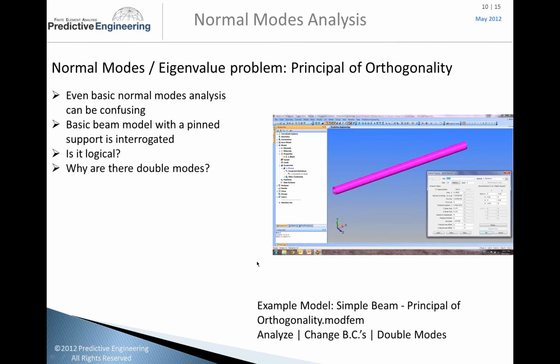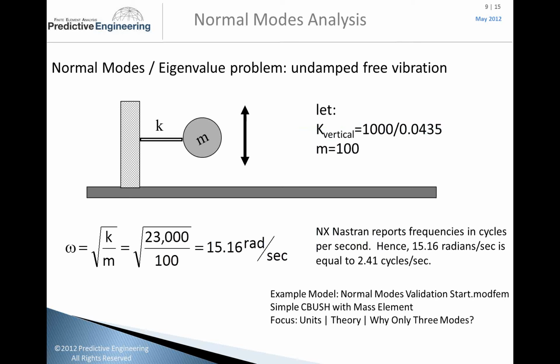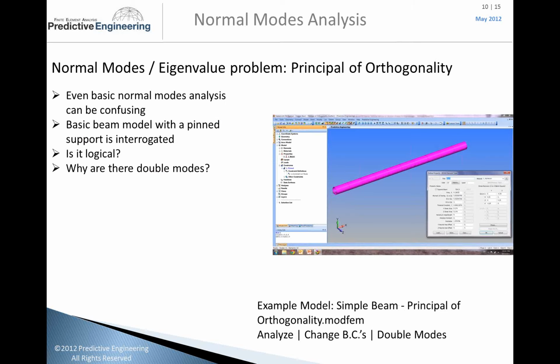I should say verifiable, because verification is where you're checking your work against hand calculations, and validation is when you check your model against experiments. So when you're modeling, that's where they say always have something where you're verifying in sections, small things to build up sort of a picture. So that takes care of that.